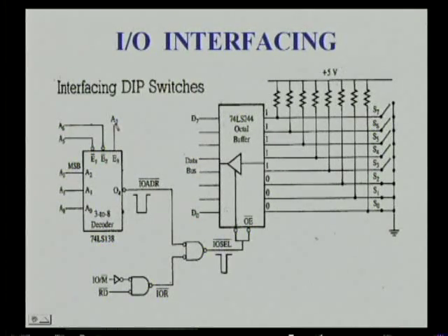So, the address will be A7 should be high, A6 should be 0, A5 should be 0, and here you see A4 and A3 signals are not used. So, this also results in multiple addresses. If we assume those as don't care conditions, and if we give 0 value to them, the first nibble will be 1000, that is 8, and the lower nibble will be 0100, that is 4. So, this particular IO device address will be 84.